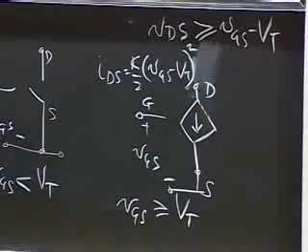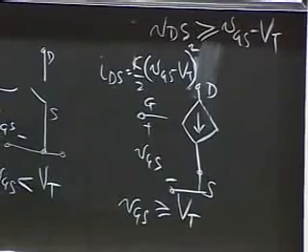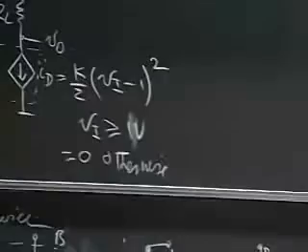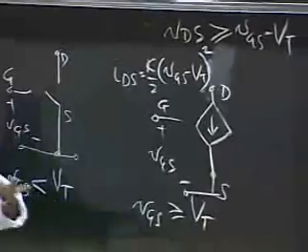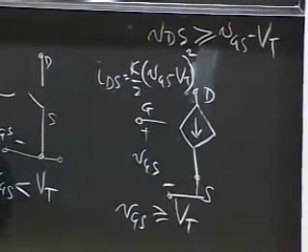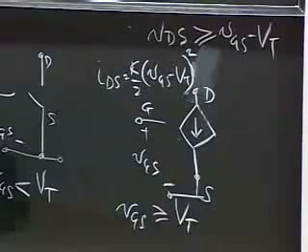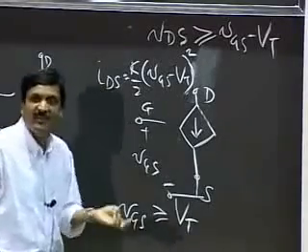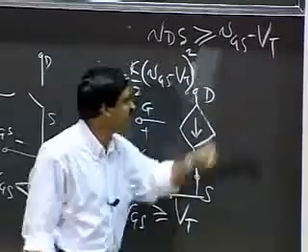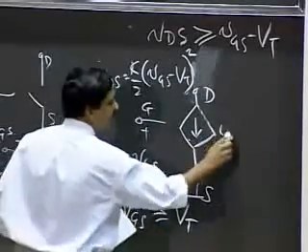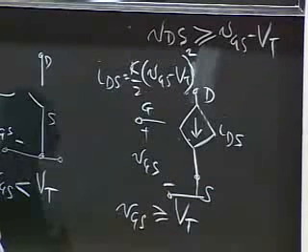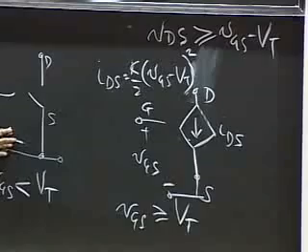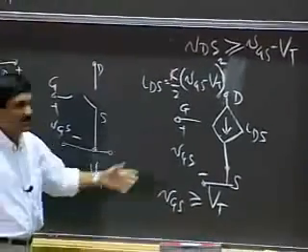Kind of reminiscent of the carefully chosen dependent source example, just that this one here is VT. So this model, which applies when VGS is greater than VT, the MOSFET has to be on, and the drain to source voltage in the MOSFET must be larger than some value, and that value is VGS minus VT, then this guy begins to behave like a current source. Okay? This model of the MOSFET is called the switch current source model.